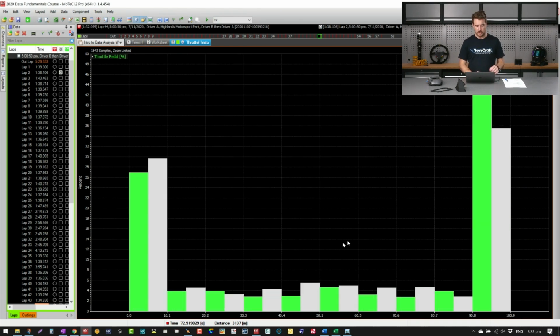little bit clearer now. So essentially what we've got on the y-axis is throttle percentage. It's been automatically scaled for us, but in this case, it's 50% and 0%. And sorry, the y-axis is the amount of time that's being spent, as a proportion of the lap, in each throttle percentage. So this is the amount of time of the lap that's being spent. And along the horizontal axis, we've got which throttle percentages. And we've got 10 sets of bars here.